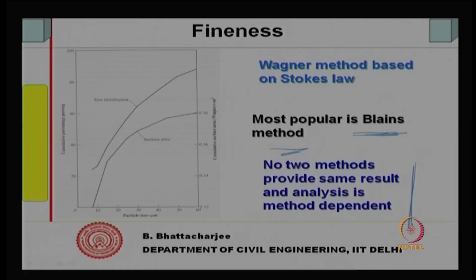analysis is method dependent. Like time of transition, as I said, whatever particle size distribution it gives, laser diffraction does not give the same thing. Neither will the hydrometer analysis give you the same thing. If you do it through microscopy, it won't give the same thing. So, every method has its own problems, but they can be used for relative comparison.